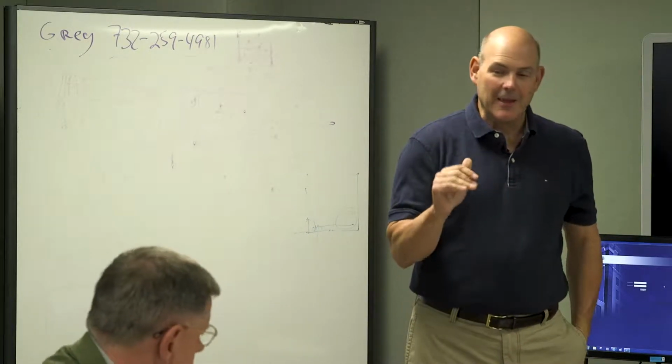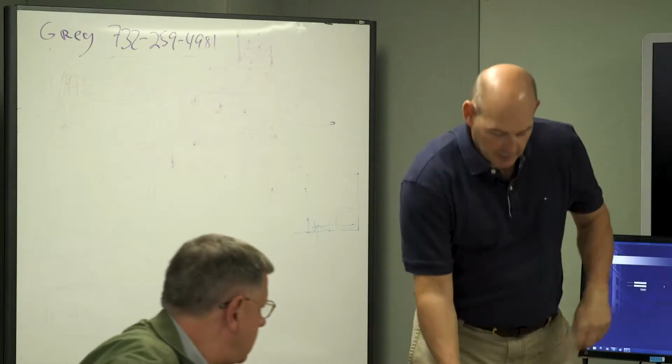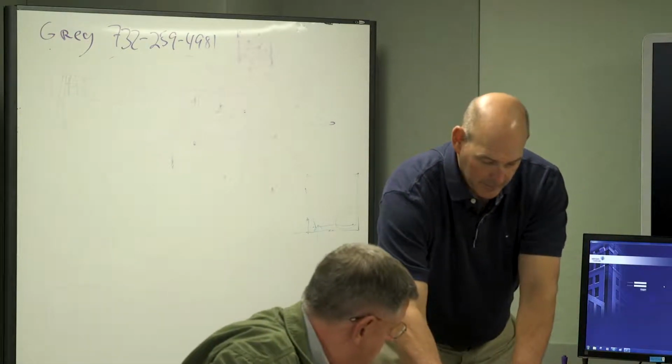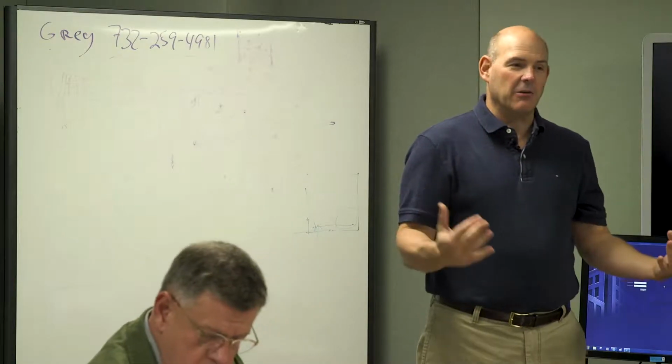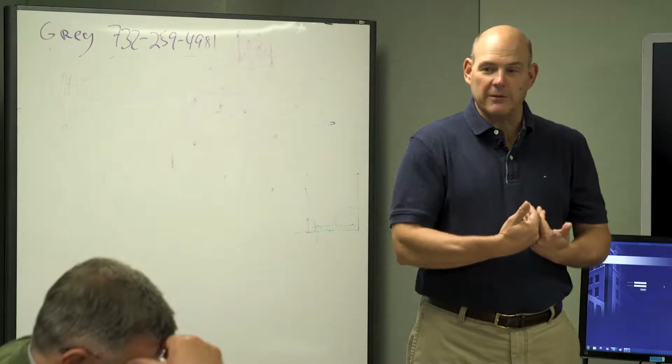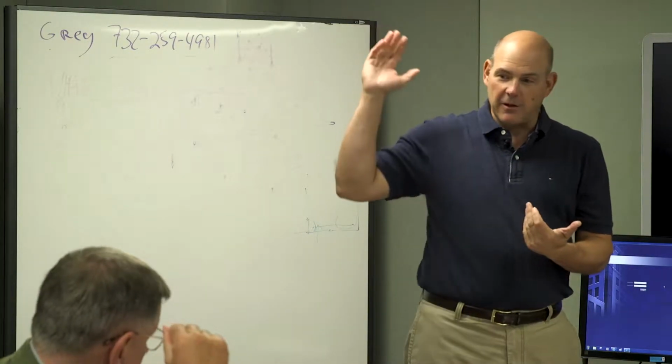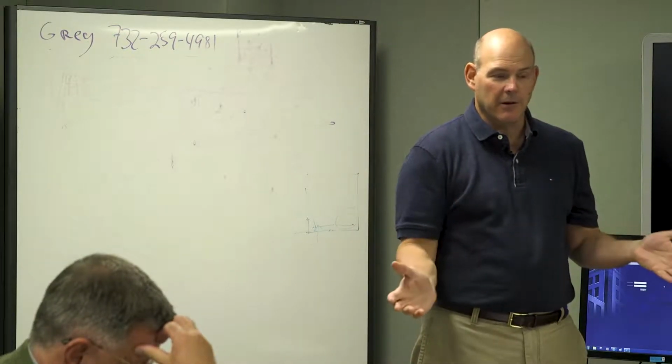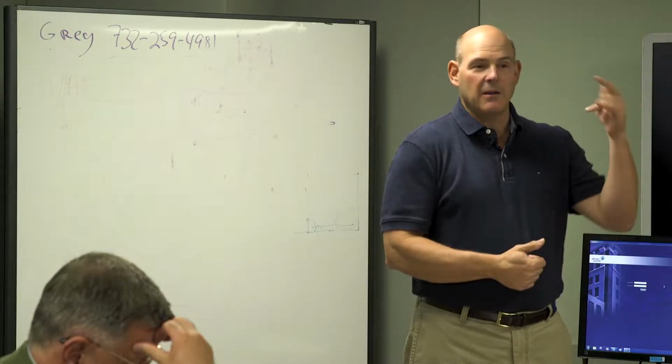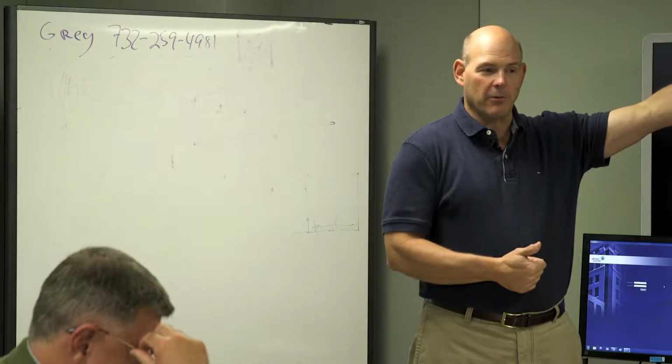If that thing fails and reads 0, that's your control point. The VFDs are going to fly up to 100% to maintain whatever the DP was. So you may just want to change the set point.